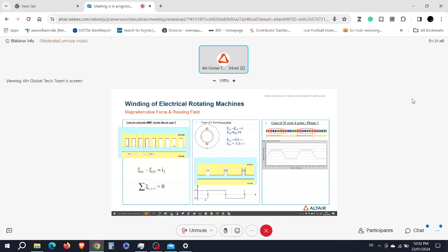And then we encounter the output, then it's minus I and we stay constant and then we put plus I. So then we will make the axis of this MMF in the middle, so we have minus I divided by 2 and plus I divided by 2. So this is for the simple way where we have input in one slot and output in one slot.